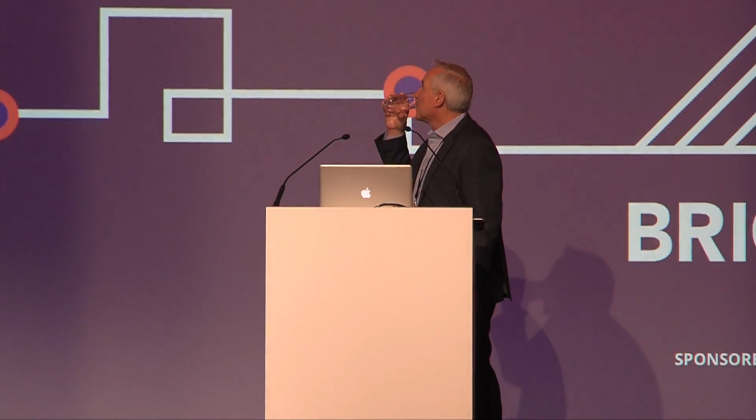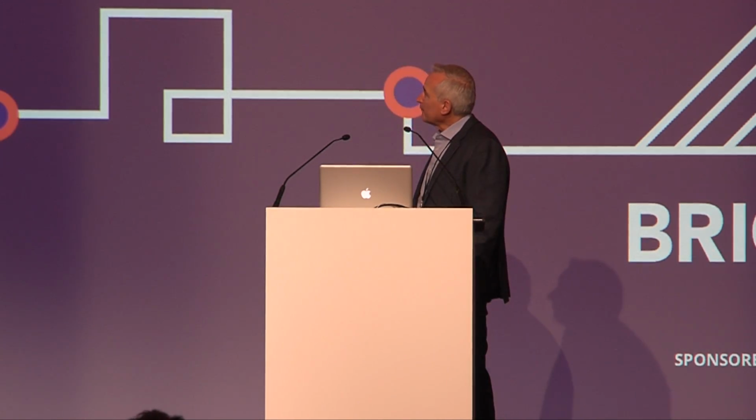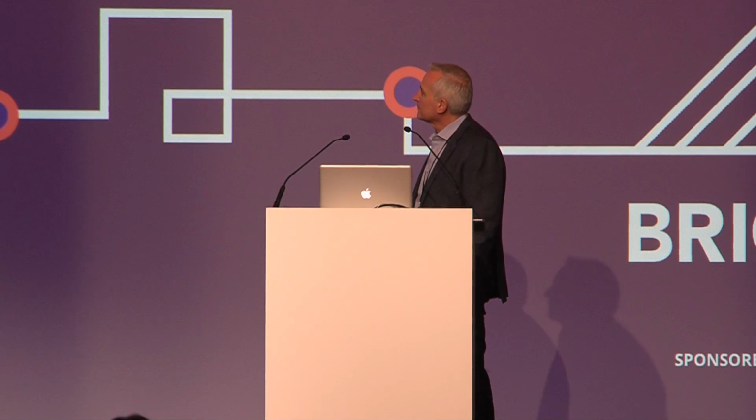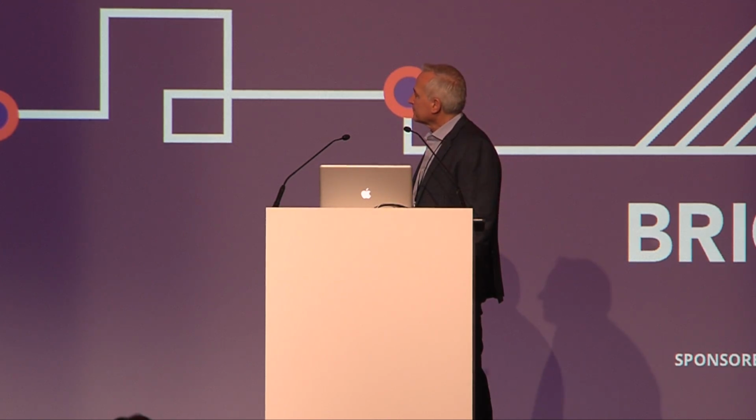So what we are going to look at now is the Drawing Explorer, which allows you to look at your drawing and to look at the metadata, like layers. What's on this layer? Or for instance, what's on this layer? And as I click on other layers, I get to see the content. So here you have the cold water pipes. And if I click 2 layers simultaneously, well, then I can see, you can add or remove stuff. So you can very quickly see what is on these layers, besides changing or creating layers, of course, and doing all kinds of stuff.